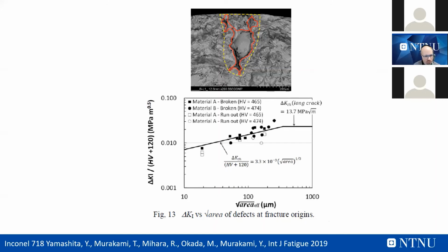This is an old picture taken from his book dealing with other materials. But what I want to mention is that if you have a defect, we have some tools developed in the past that can be useful to predict the fatigue life of your component. And actually, additive materials and the Murakami method are very interesting because they can be connected together, and the Murakami method can be easily applied to additive material in the presence of defects. So this is an interesting point that I want to mention today.